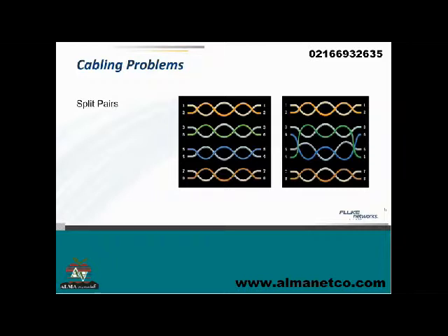So if you want to run 2.5 gig on your Cat5e cable, you shouldn't have any problems if it was certified and you know it's Cat5e. But if you want to run the 5 gig, you may have to go in and do a little bit of retesting. The testing that's required is around alien crosstalk. If you have cable in bundles, you not only get crosstalk between the pairs in the jacket, but between adjacent pairs. And there are ways to test for that, and if you have a contractor that knows how to do that, that's the way to check for that.